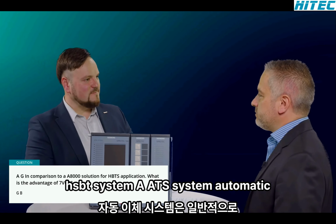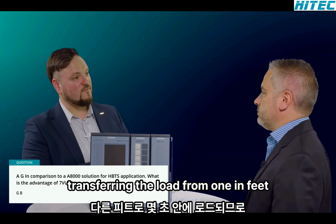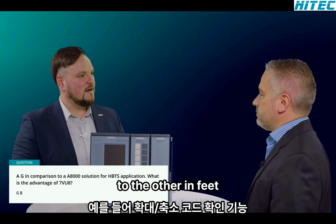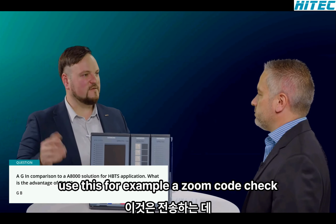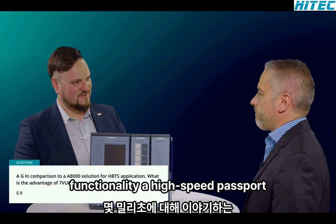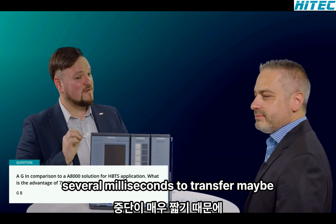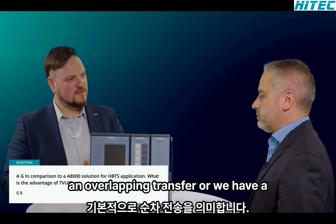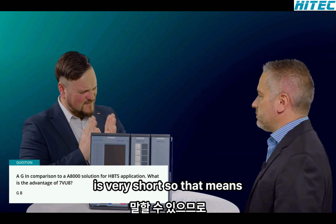So there is a difference between an ATS system and an HSBT system. An ATS system, automatic transfer system, is normally transferring the load from one in-feed to the other in-feed in several seconds. Therefore, we use, for example, the sync check functionality. With a high-speed busbar transfer system, and this is the difference, high-speed, we talk about several milliseconds to transfer. Maybe an overlapping transfer, or we have a short interruption, but the interruption is very short.